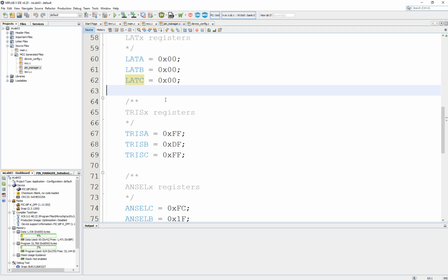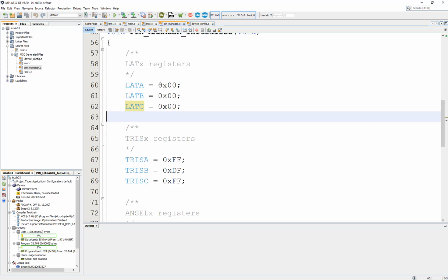But before we move forward, let's see. 0, 0 to the output buffer. What is this doing? I'm just clearing all the values in it, just in case it stored something previously, okay? Because these are output registers, I'm going to write into these registers later in the code. But before we do anything, I just want to reset it. Just clean, nothing in it.